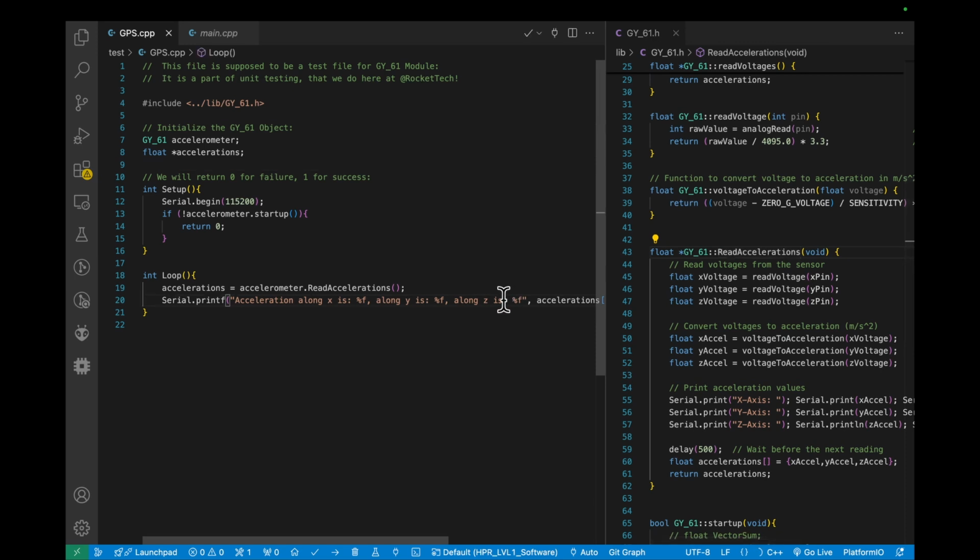Hopefully, does it crash? Also we need to delay it a little bit. Why? Because the frequency that this thing runs at is in gigahertz, which is like 10 to the power 9, but the sensor cannot output values that fast. So we're gonna have to put in a little bit of delay, let's say 100 milliseconds or 150 milliseconds, for giving the sensor a little bit of time to output a new value. Otherwise this loop will run like crazy fast.